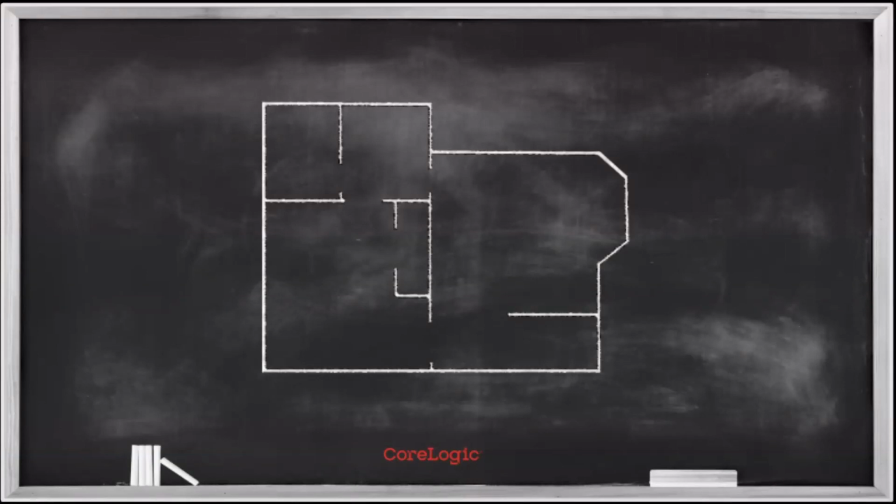Now, to really know how many chambers you have, you take an initial guesstimate, right? Just like with class, it's an initial guess. Looking at this floor plan, I see openings between all of these rooms, and those openings are standard door widths, and I can provide ample airflow through a standard door opening. There's no obstruction there that prevents me from doing that. So there's nothing here that would indicate that I have a restriction to my circulation between any of these spaces. And that's what I'm going to look for. Is there an area where there is a reasonable restriction that is going to prevent me from circulating air between two or more of these rooms? And if I see that, then we are going to have separate chambers as my initial estimate.